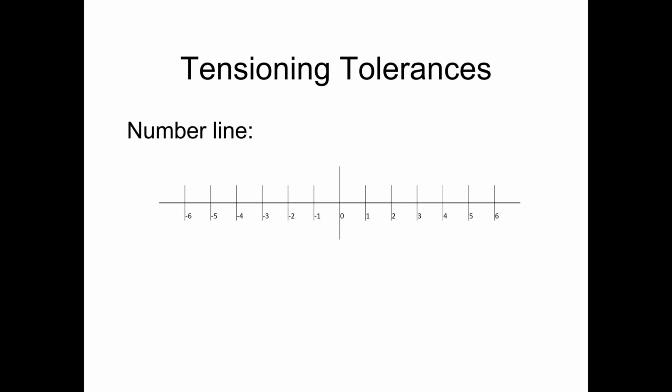But let's say that we choose to tension the strand and we go 3% over on our force. So that means that our force would be right there at the plus 3% value. When we measure the elongation for that strand, we measure an elongation that's 3% under the calculated elongation. So that would put us right here on our elongation.